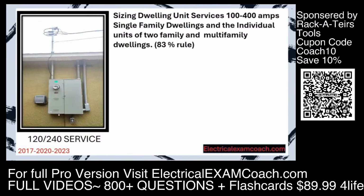Now let's learn how to size dwelling unit services and feeders between 1 and 400 amps. This applies to single-family dwelling units and the individual units of two-family and multifamily dwelling units, and it's affectionately called the 83% rule.